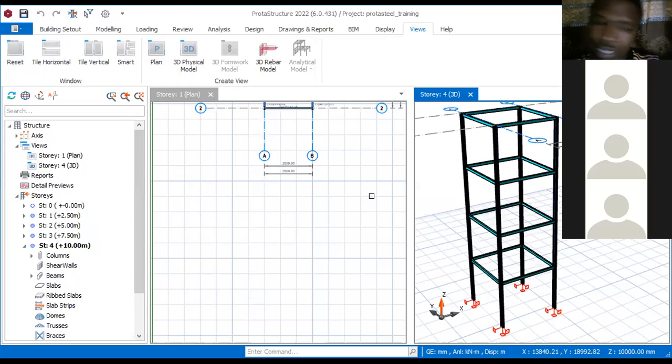But sometimes even that 12 meters is not up to length, so it's safer to design assuming 11 meters, because when you measure it, it's often not up to. But let's say it's 12 meters. You have your column 12 meters running all through, then you have your brace at 2.5 meters. I think that's what he is trying to talk about.